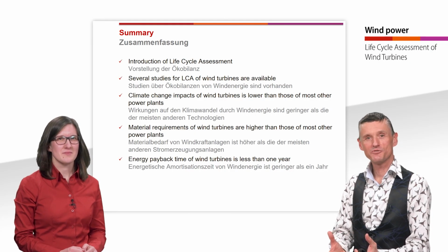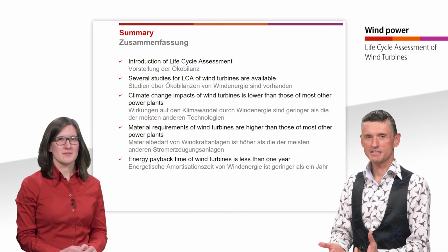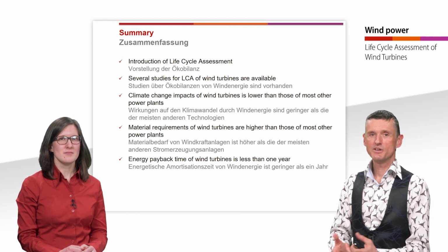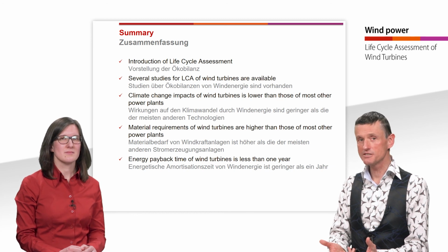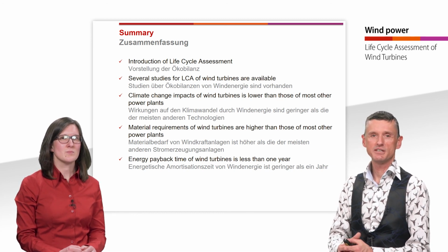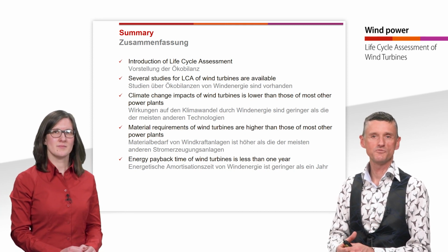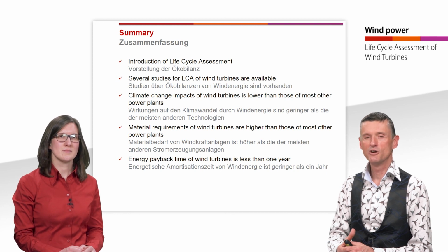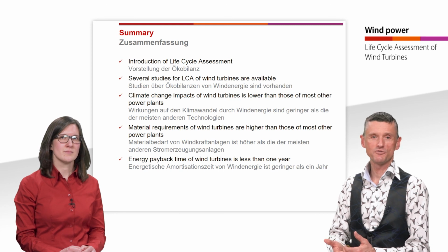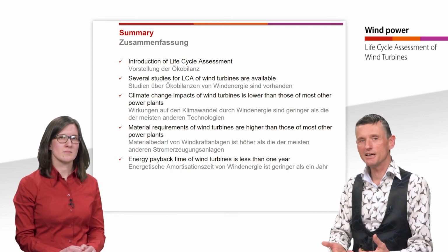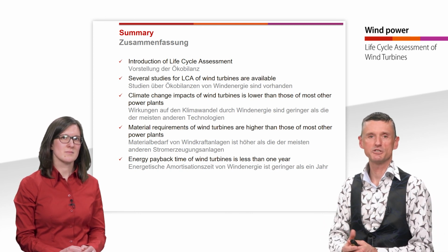And then we conclude what we have seen in this video. First, we have had an introduction on life cycle assessment and how we can do that. We have seen that there are several studies on LCA for wind turbines. And in those studies, we have seen that the climate change impacts of wind turbines are significantly lower than those of most other power plants. On the other hand, the material requirements of wind turbines are higher than those of most other power plants. Again, stressing the importance of going into a recycling process for those technologies.